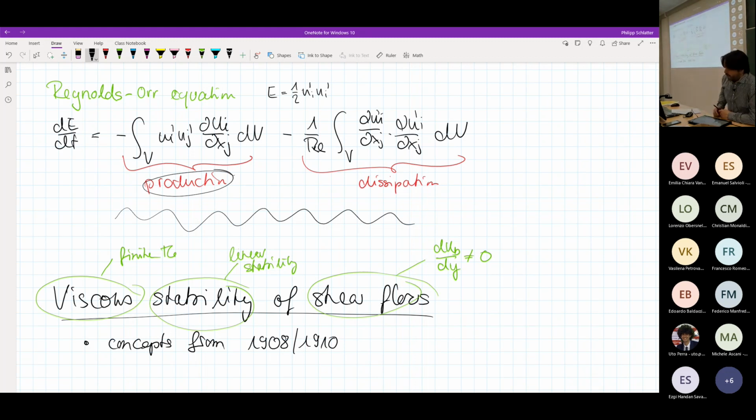Okay, good. So we saw that there's always a balance between production and dissipation in a flow. Actually, the importance of this is that both production and dissipation originate from linear terms in the Navier-Stokes equations. The nonlinear term, the advection term, resulted in a triple correlation, which we could neglect because it was a divergence term, a transport term, because of the conservation properties of the Navier-Stokes equations.